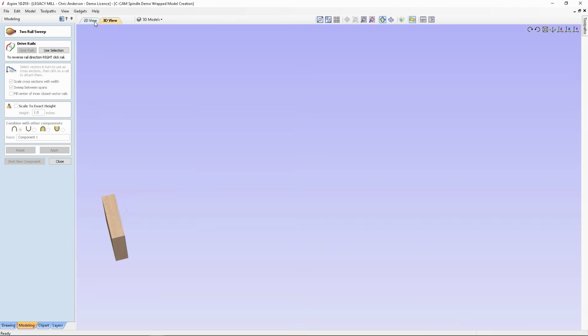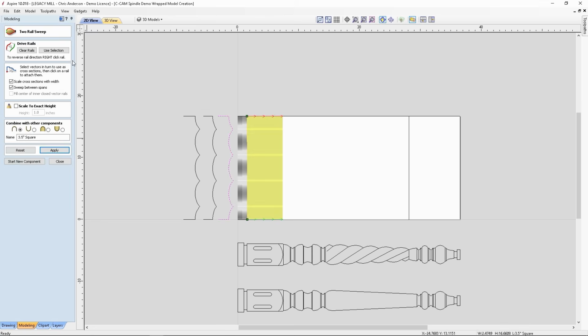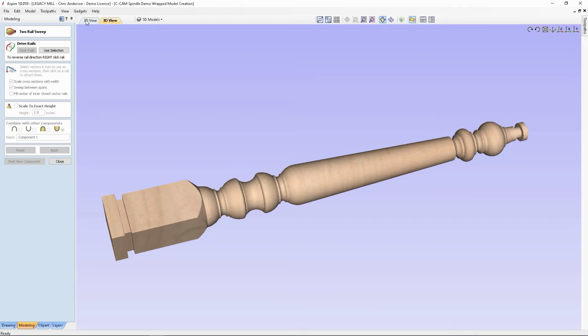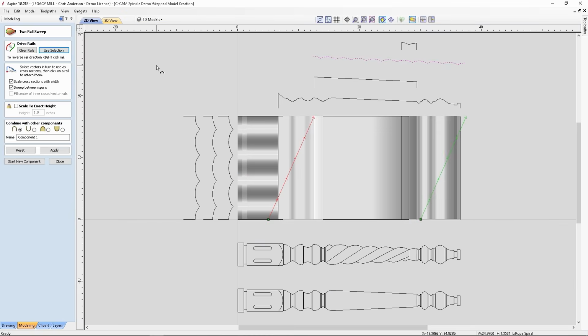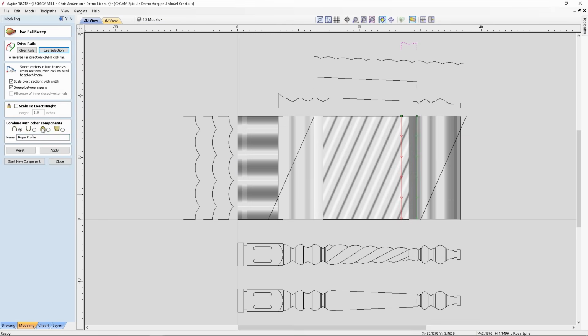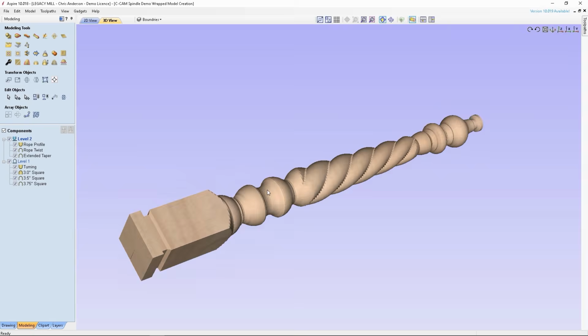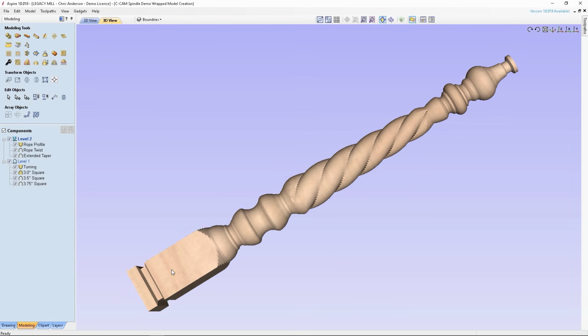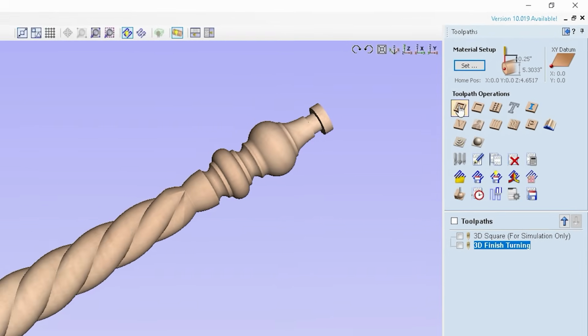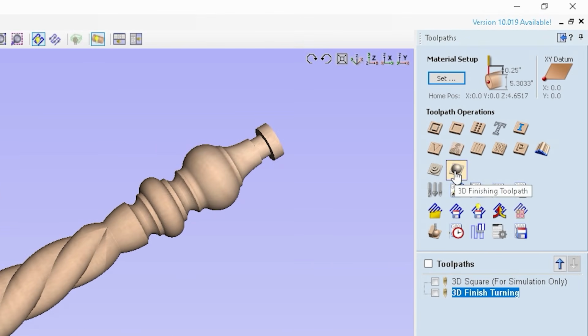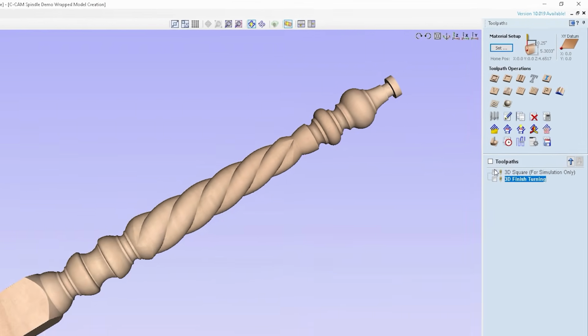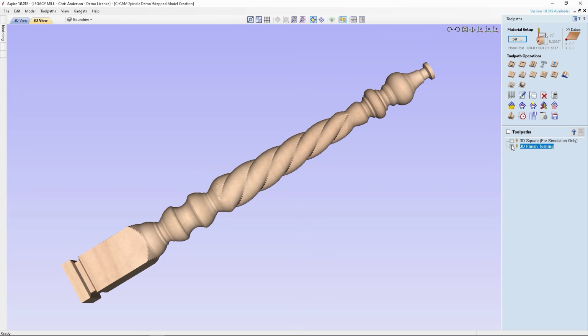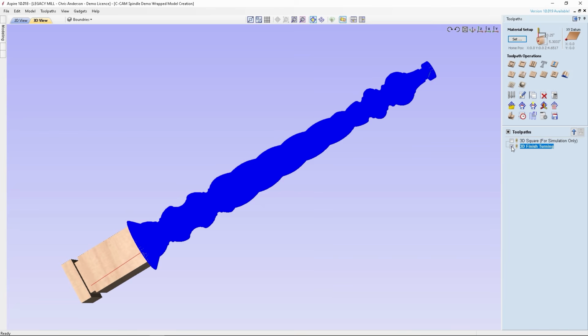Well, first, from a 2D CAD drawing, a 3D model needs to be created. Based on the complexity of the model, this process is daunting and could take a long time. Next, our model is ready to program a series of toolpaths. For CNC machines with 4-axis capabilities, there are only 2 toolpath options: indexing and 3D carving. Traditional CAD/CAM software forces us to separate both cutting techniques into 2 separate programs.